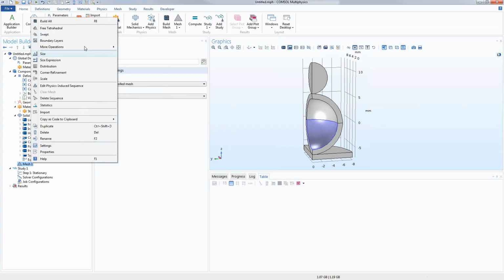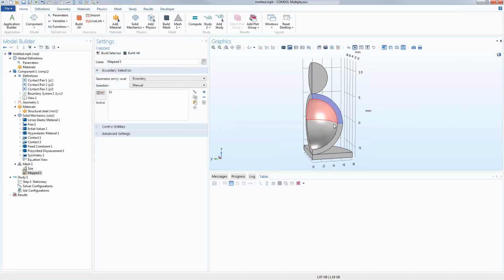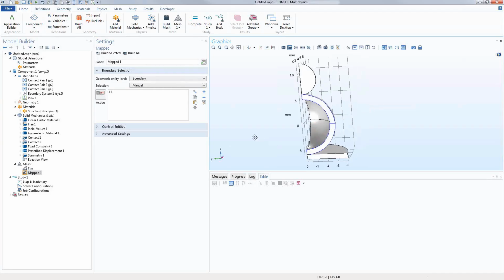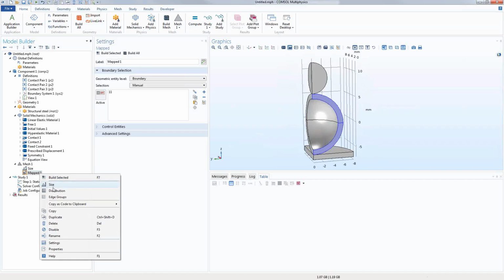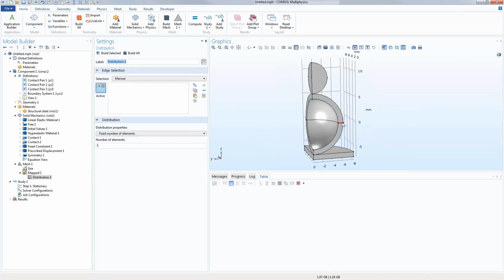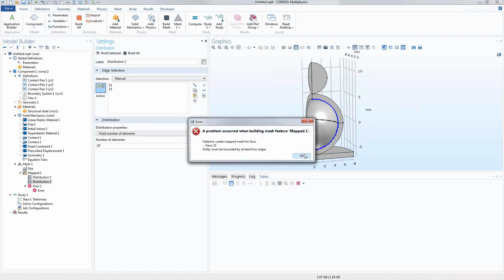elements, what I'll do is first create a two-dimensional rectangular mesh on the cross-sectional boundary of this hyperelastic material. And by doing this, I'll also have explicit control over the number of elements. So let's say I want 3 elements across the thickness of the spherical shell, and about 20 elements on these circular arcs of this spherical shell, 10 each. So that builds a 2D.